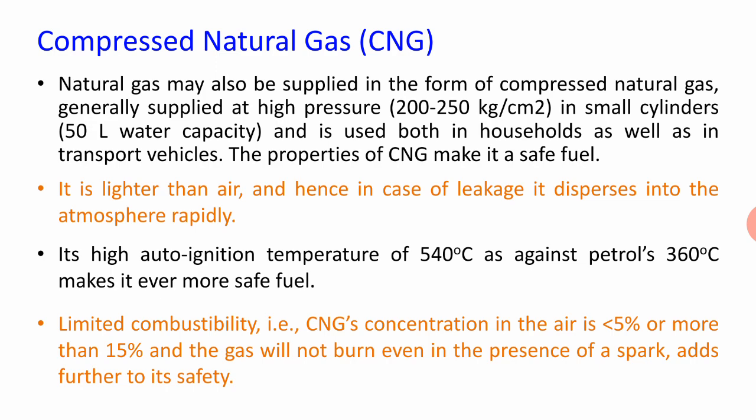If the concentration of CNG in the air is less than 5% or more than 15%, the gas will not burn even in the presence of a spark, which adds further to its safety. So there is a limit, meaning it must be between 5% and 15%. If it is beyond that or less than that, it will not ignite.